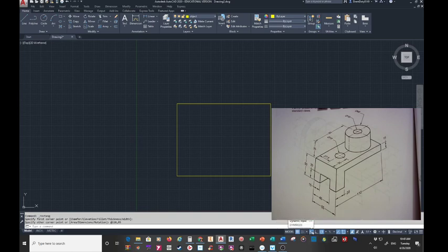If it is darkened in, at least in 2020, then it's on. So here are the things that I have turned on. The grid doesn't matter, I just have it as a background. I don't use it. I don't use Snap. They're just really annoying and I don't like them. I have dynamic on. I do not use ortho because it only goes up and down and left and right. I use polar.